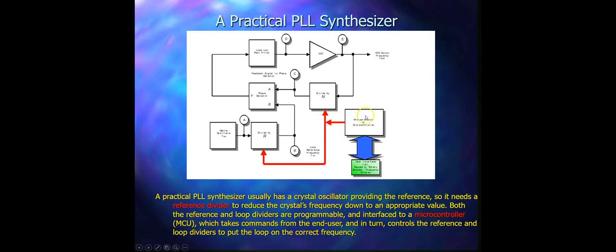It is basically used to issue commands to the various parts of the phase locked loop system by sending digital values to each of the PLL registers. For example, these registers are this one and this one. So the PLL shown here has two stages that must be programmed by the software, which are the N register and the R register, and the software basically controls all of these actions from here.